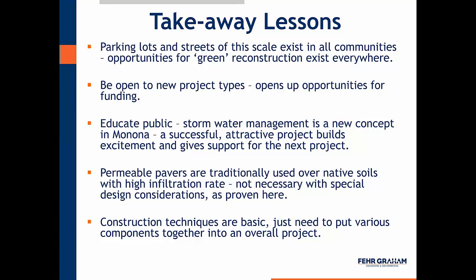Permeable pavers are traditionally used over native soils with a high infiltration rate. We didn't have that here. We had a fairly tight clay, but as you can see, with some special design considerations, we can make it work. It will work. And the construction techniques are basic, nothing unusual. As you saw in the slides, we just need to put the various components together and turn it into the overall project.